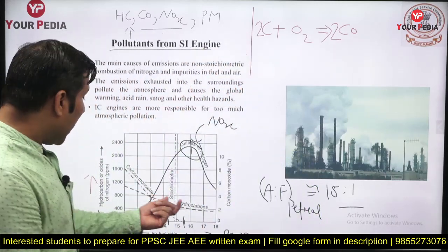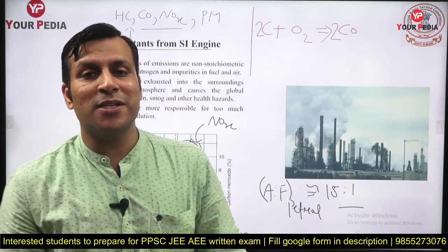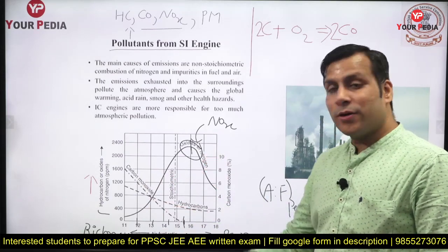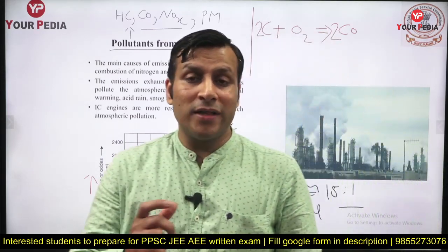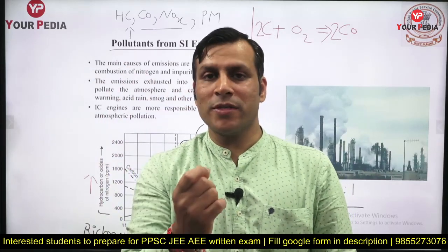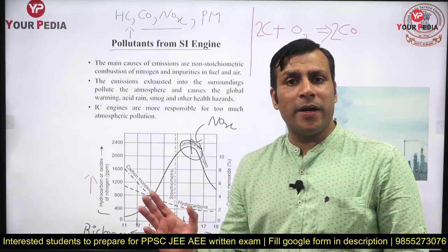Otherwise, if you talk about the hydrocarbon and carbon monoxide emission, what do you think, guys? Is carbon monoxide or hydrocarbon emission higher in petrol or diesel? Generally students think, sir, diesel engines develop more pollutants as compared to petrol engines, but it is not like that, guys. The carbon monoxide and hydrocarbon emission is more in the petrol engine. Why? One thing, petrol is more volatile, it easily evaporates, whereas if you are keeping diesel in a tank, the evaporative losses are very less, because it is not a volatile fuel as compared to petrol.